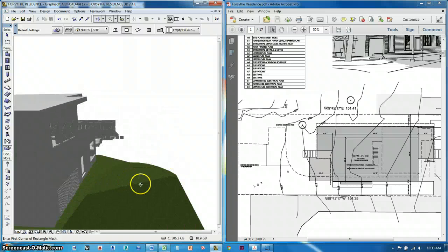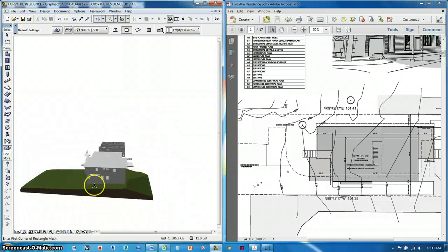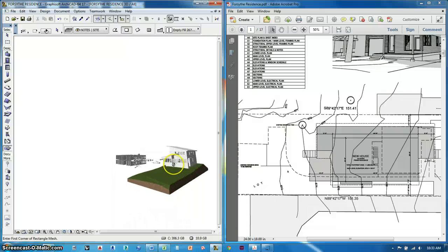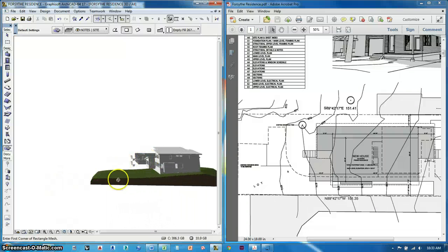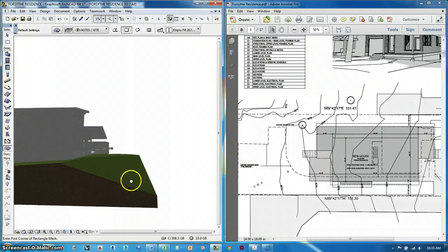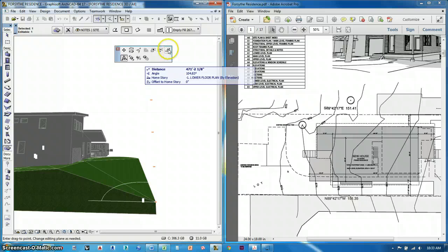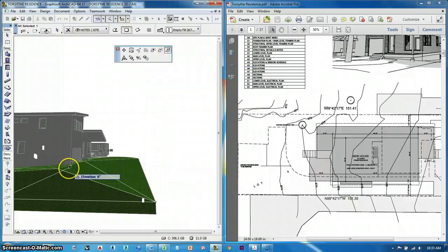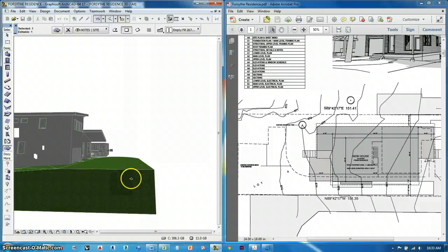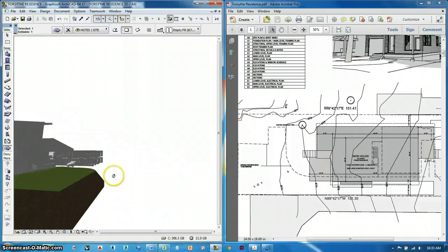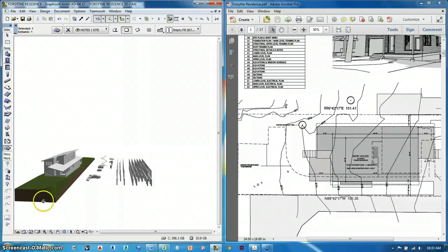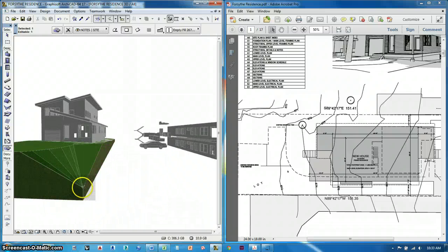So yeah, we got the corners, right? The corners are off. We're doing okay, but the corners are off. So what I can do here is I can select my node, select the mesh, excuse me, go on this check mark right there, Z, and if I hold down the shift key, I can snap to that point. Take this guy, snap to that point.